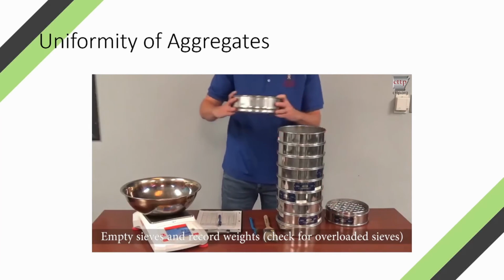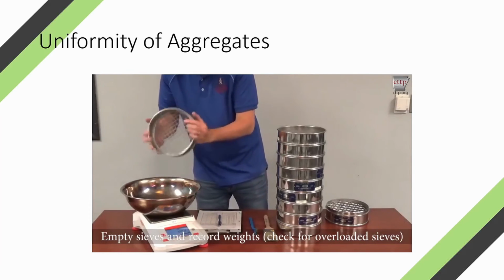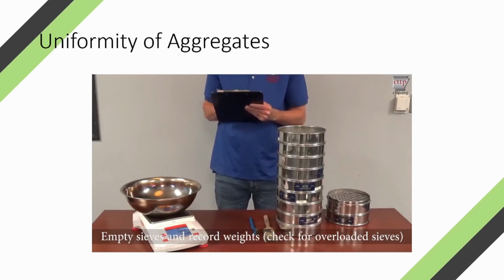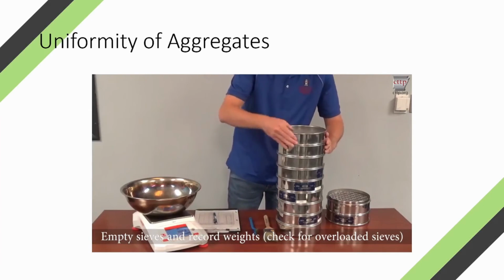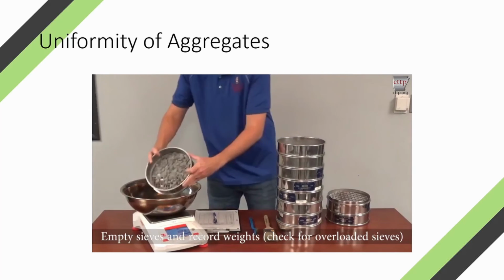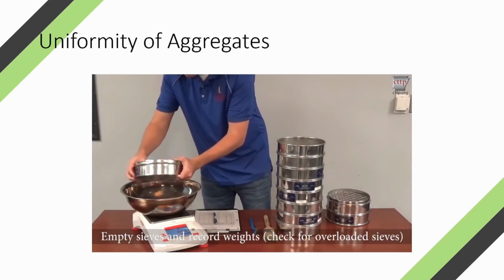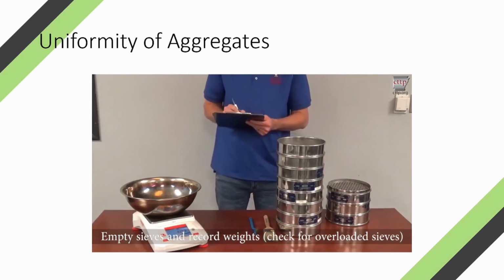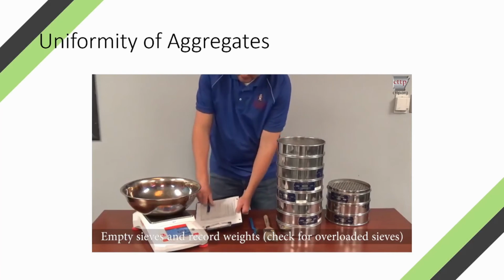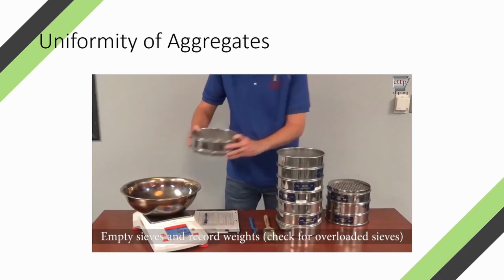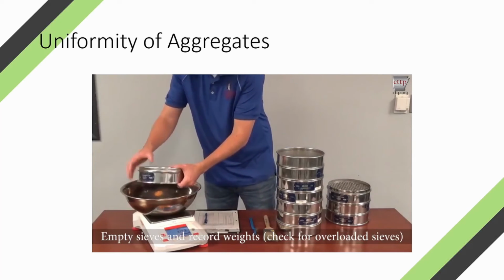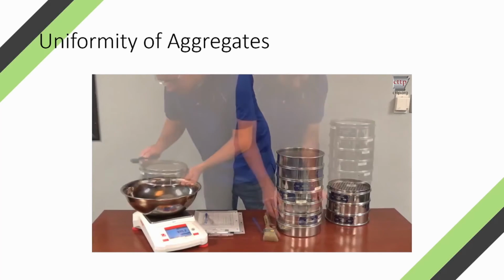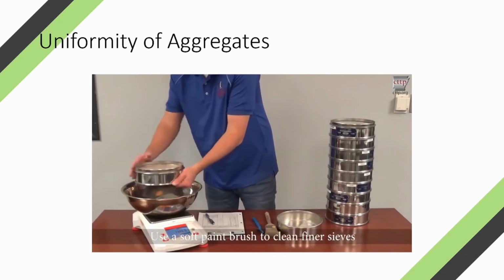Note that individual or cumulative weights may be recorded, and the method chosen will affect subsequent calculations. Use a soft paintbrush to clean finer sieves.